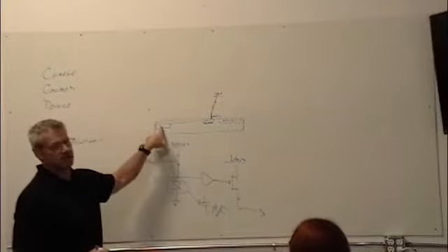So here you have your vertical shift register, and here you have your horizontal shift register. And now what have you done? And you've still got your guards. You've gone from the magical, 99-ish% fill factor. You've knocked yourself down to maybe 95 or 90. I've seen 80, maybe 80. Now it's still better than the CMOS.